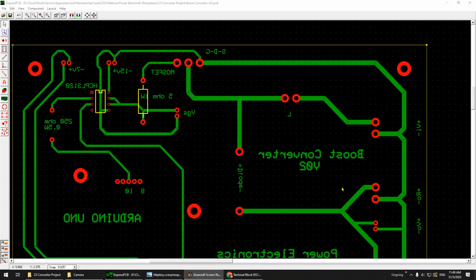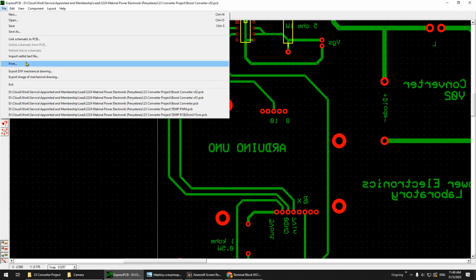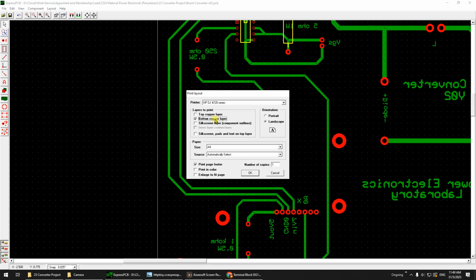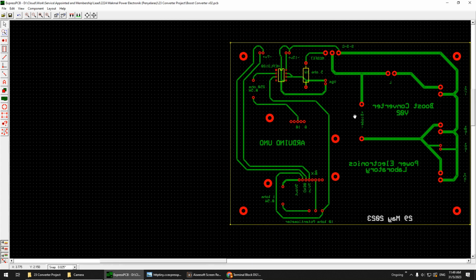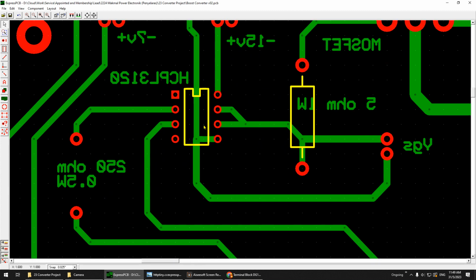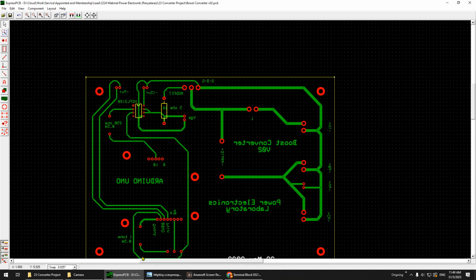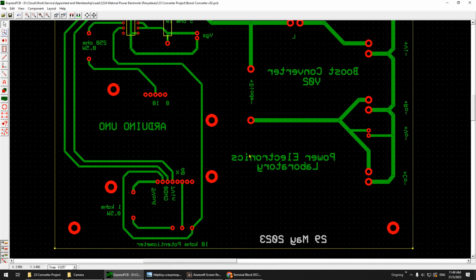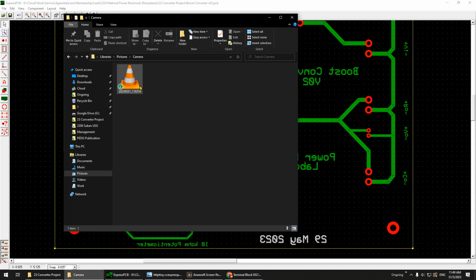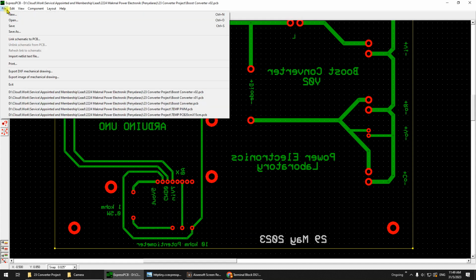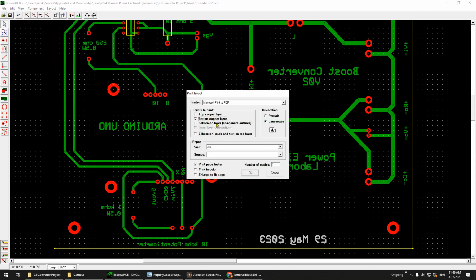After you have designed everything like this, you can just print it. Print only the bottom layer, and make sure the size is correct. Size is important, because if you choose the wrong size, it cannot fit. After you print it, you have to test it first. You cannot just directly do this. Like I said before, you print at the bottom: file, print, bottom side, because you're using DIP. Of course your design is also at the bottom side. SMD is at the top side, but like I said before, for FKE, UTM, we don't have a good facility for SMD, so I suggest you do the DIP.